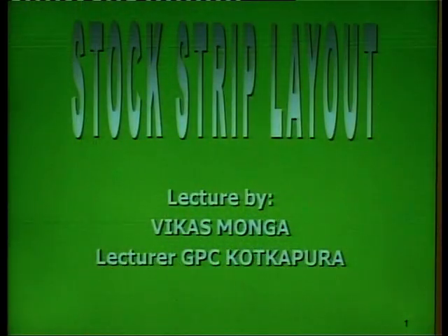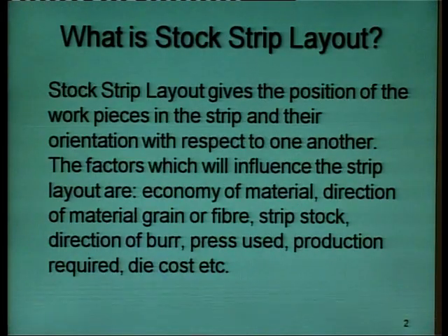Good afternoon, everybody. Today I am going to present a lecture on the topic stock strip layout. So, let me tell you what stock layout is. Stock strip layout gives the position of the workpiece in the strip and its orientation with respect to one another. It means whether the workpiece is in vertical or horizontal position, and even the direction has to be considered when we consider the stock strip layout.